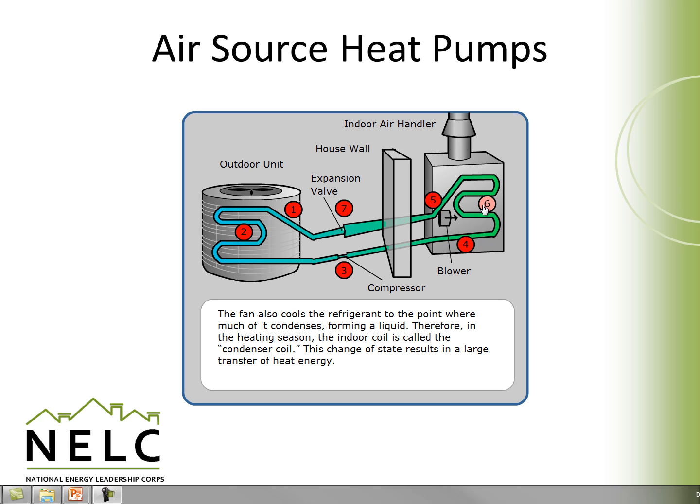The fan also cools the refrigerant to a point where much of it condenses back into a liquid, and therefore in a heating system the indoor coil is called the condenser coil. This change in state also results in a big, substantial transfer of heat energy.